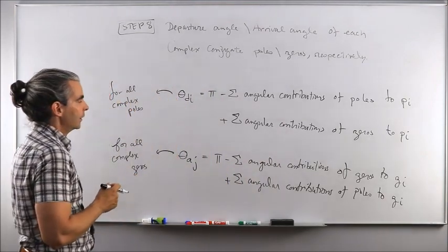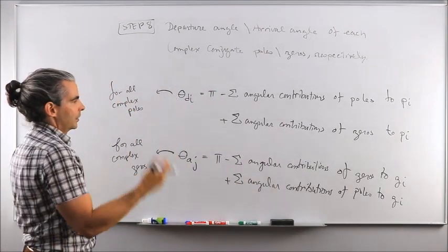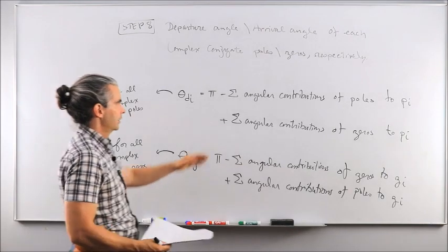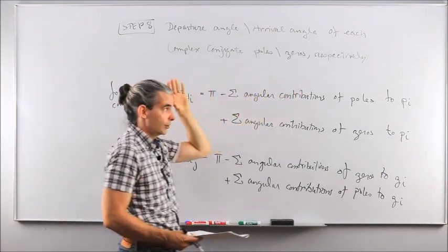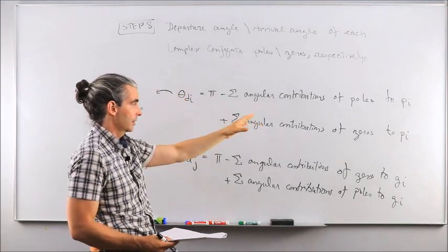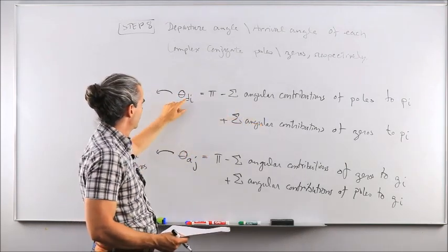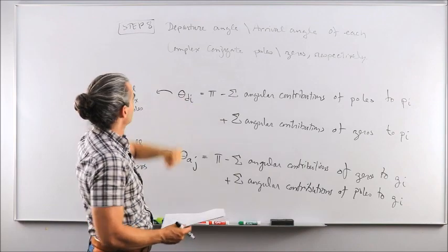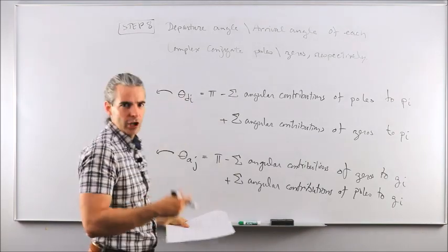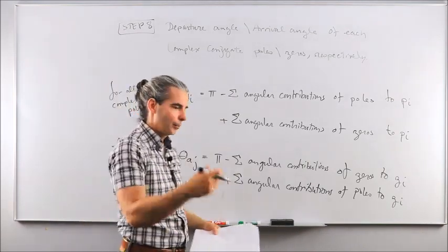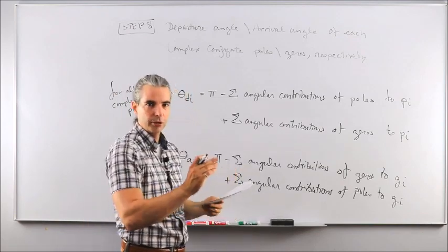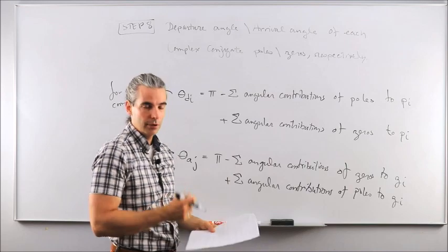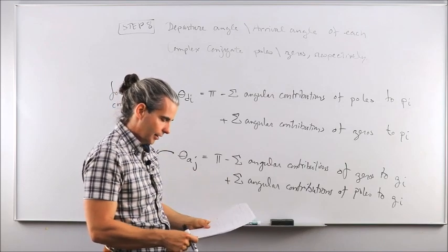Okay? We'll see with practical numbers how we can determine the individual contribution for each other poles and of all other zeros in the complex plane onto a given one. It's just trigonometry, okay? Knowing the real part, the imaginary part, how can you figure out the relative angle between one pole to, say, another zero? It's just by using trigonometry.